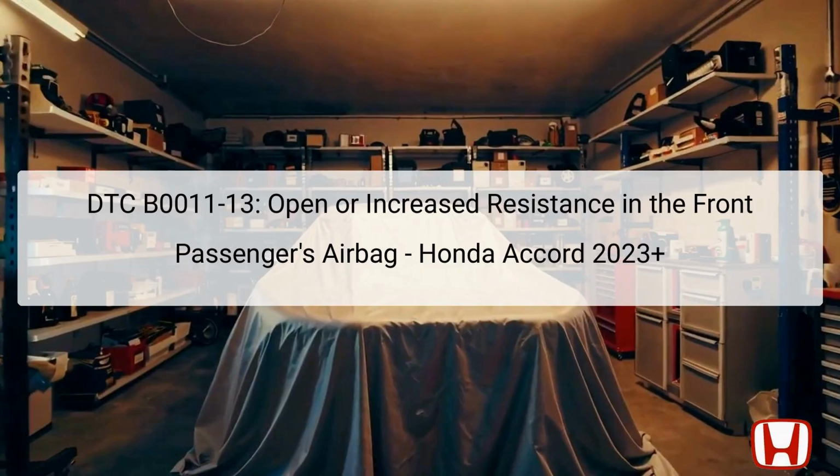In this presentation, we are addressing Diagnostic Trouble Code DTC B0011-13 associated with the front passenger's airbag in the Honda Accord 2023 and later models. This specific code indicates an issue regarding open circuits or increased resistance in the airbag's second inflator.